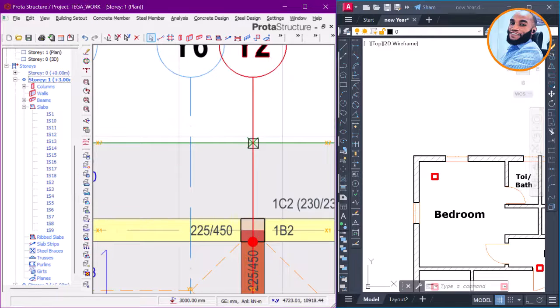It is directly on the slab here, and basically how load is being transferred when it comes to structure: load from column is meant to transfer to the beam below. Load does not transfer to the slab directly, except if it is a flat slab. So column load must transfer to the beam below.